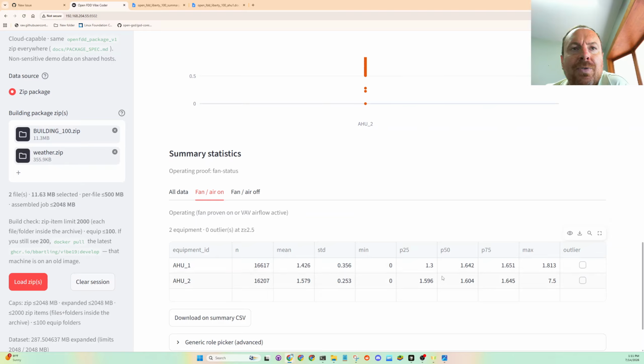But yeah, air handling unit 1, this system has some goofy things going on, where if there are components downstream that aren't working right, it'll mess up upstream components like the fan control. Something is going on. A little bit deeper dive in this building is required, in my opinion.